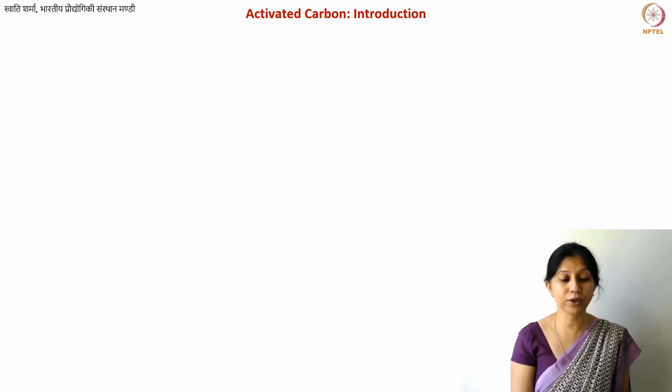This lecture, we are going to move on to activated carbons. Activated carbons are also a form of non-graphitizing carbons, and they are formed by the charring process that you know already. The polymer precursor does not undergo a semi-solid phase after its degradation, and that is why, even though there will be some shrinkage, there will be more pores rather than shrinkage in these carbons, because the skeleton of the polymer is preserved more or less.